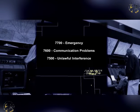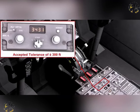Any SSR code changes will be kept to a minimum to reduce pilot and controller workload. Where necessary, individual aircraft identification codes can be issued, for example to humanitarian relief, medical or VVIP flights. When Mode Charlie, the altitude reporting element of an SSR system, is used, it must conform to a tolerance of plus or minus 300 feet.